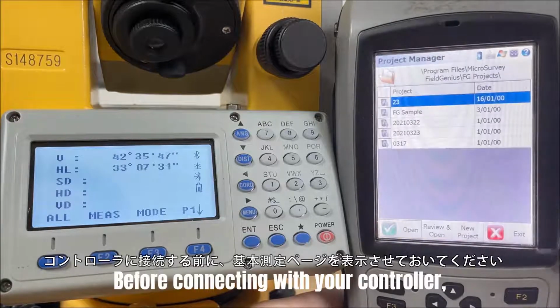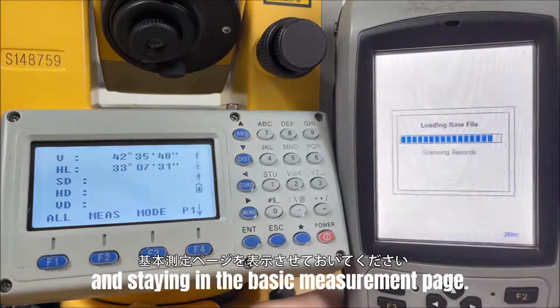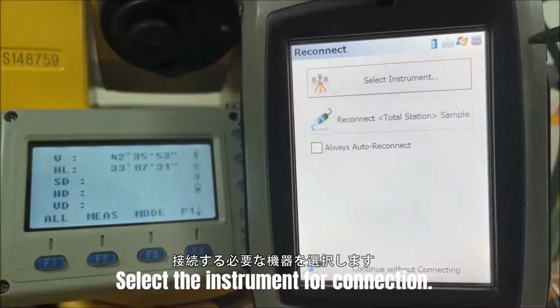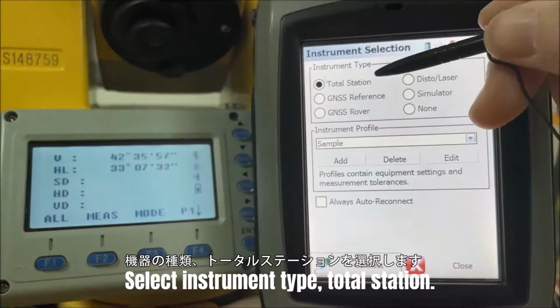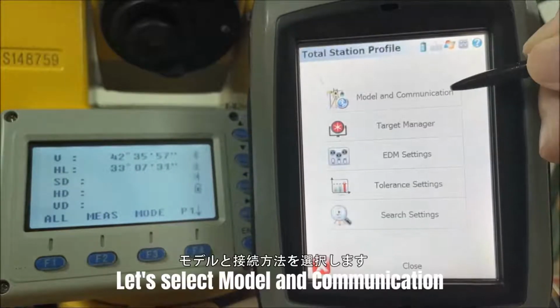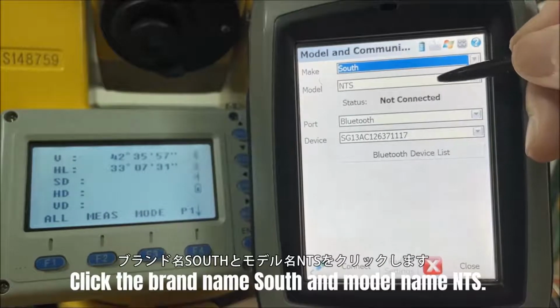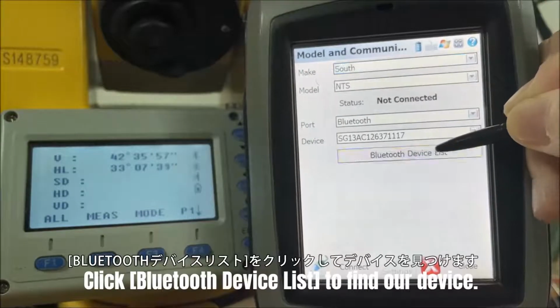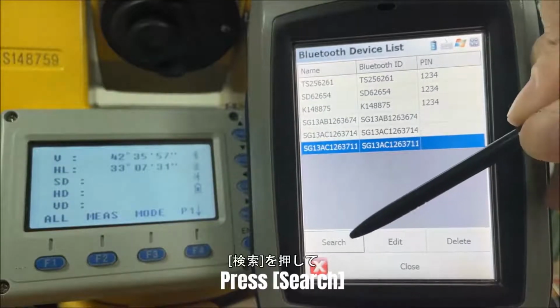Before connecting with your controller, please start your total station and stay on the basic measurement page. Select the instrument for connection. Select instrument type, total station, and click Edit. Let's select Model and Communication, click the brand name South and model name NTS. Click Bluetooth device list to find our device. Press Search to search for the device.